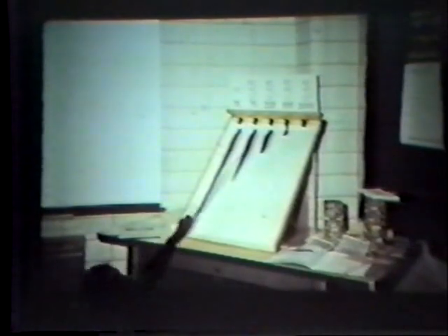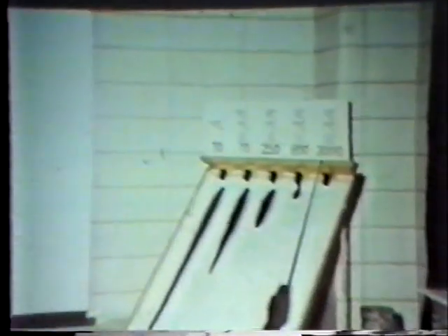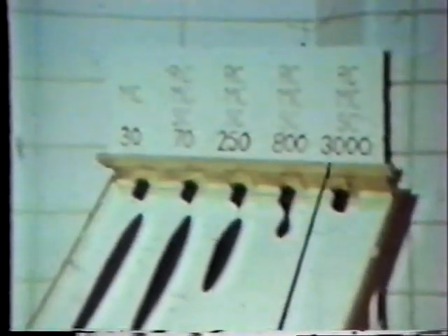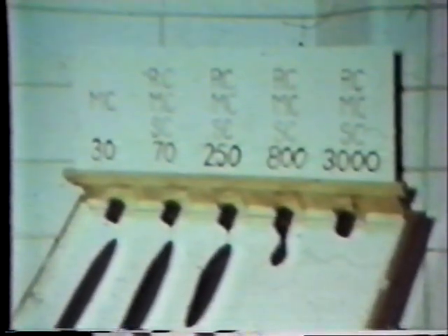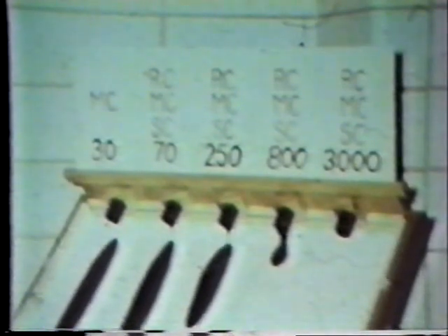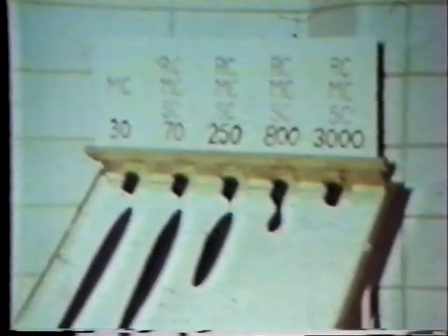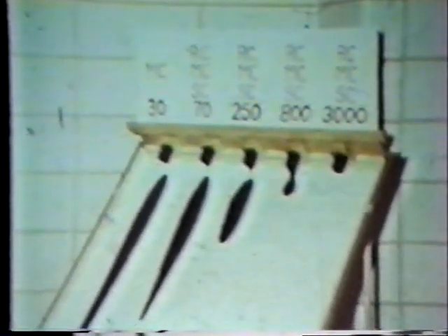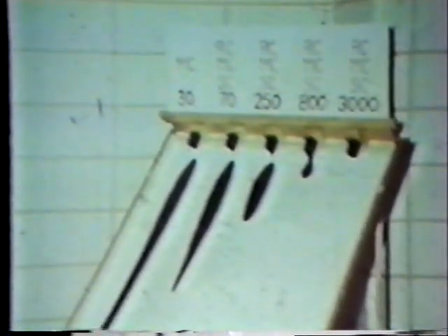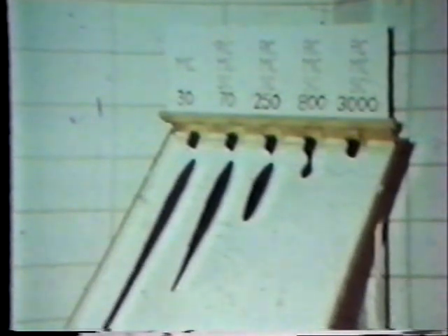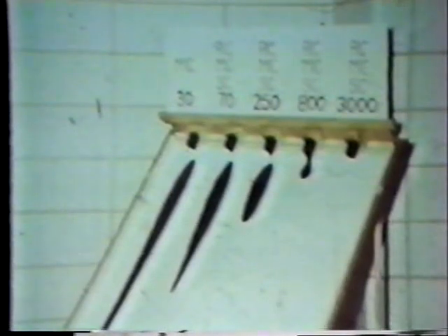First of all, I mentioned to you that there are three different grades of asphalt in terms of the way they cure out, RC, MC, and SC, as you can see here. And then I said that the viscosity is very important also. So in the cutback range, we have 5 different viscosities. And the reason, as I'm sure you can see perhaps, if you're doing something like dust laying, that's the kind of material you want to use, something very thin that'll penetrate in or prime.